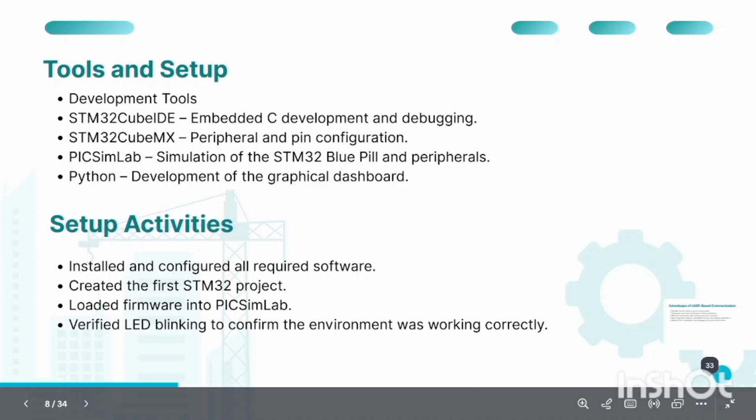Development environment and workflow. Our tools use STM32CubeMX for peripheral-based register initialization and pin mapping. Firmware was written in embedded C using STM32CubeIDE. Hardware and loop behavior was verified in the Proteus Lab emulator, and the initial pipeline integrity was confirmed through a non-blocking LED blinking test.